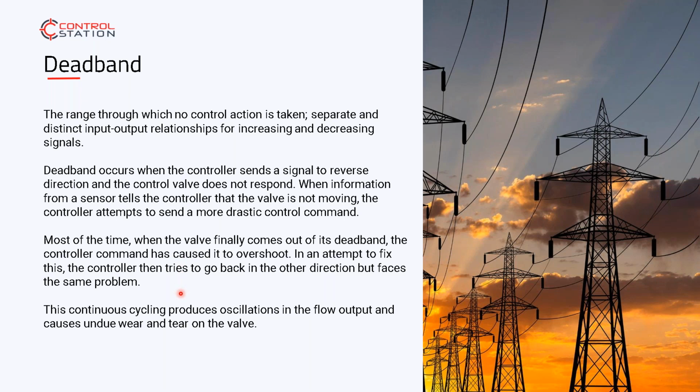The detection of it is that when you reverse direction and you get no motion. Typically, stiction will work in both directions, because that stiction is overcoming that static friction, whereas deadband tends to, you can work up the stroke, up the opening of the valve very effectively, but when you change direction, you have to take up all of that slack in the mechanicals of the process before it will re-engage or affect the change in the other direction.